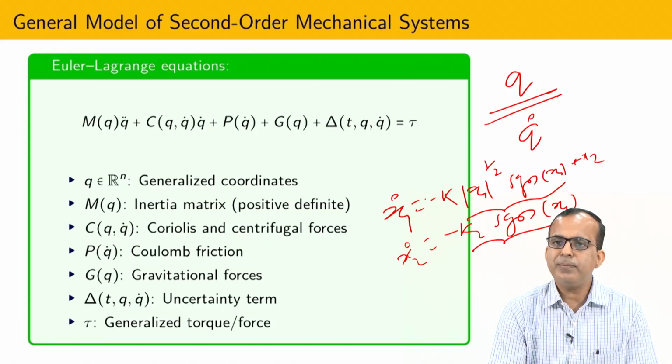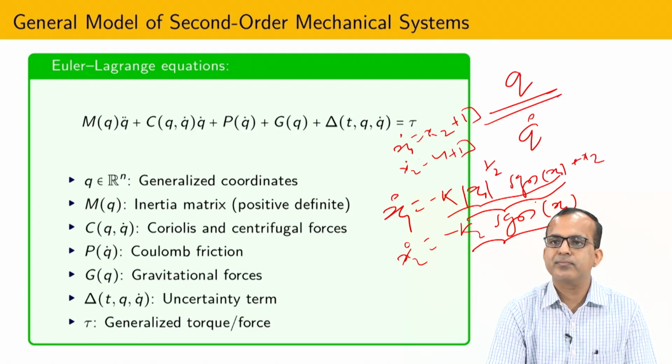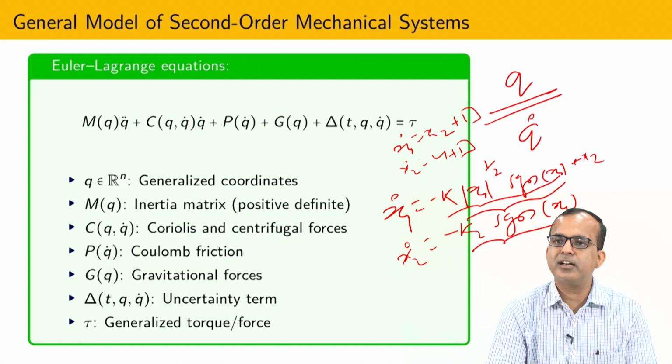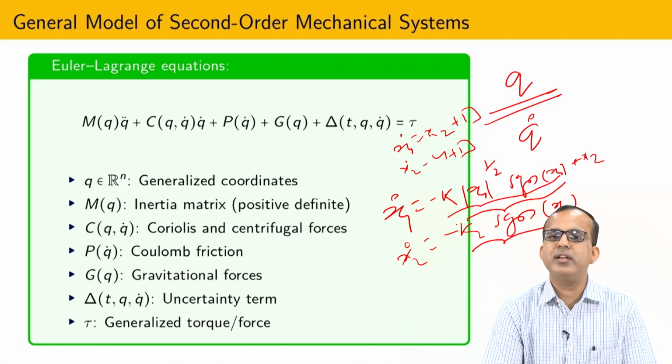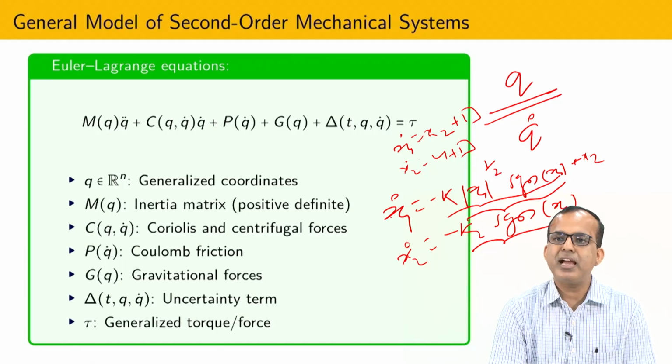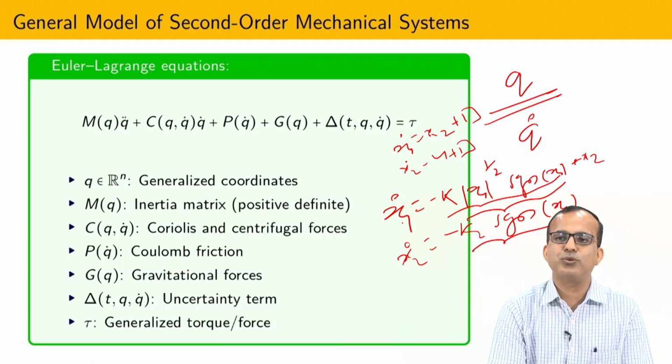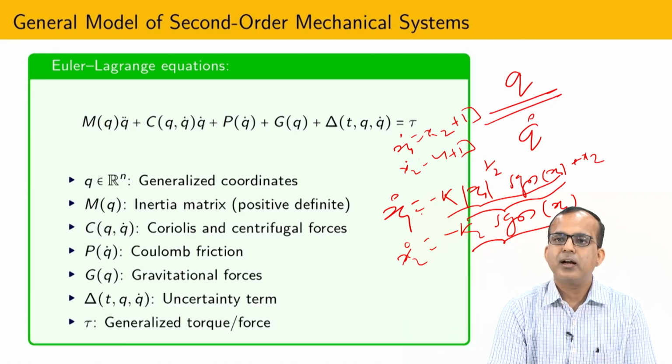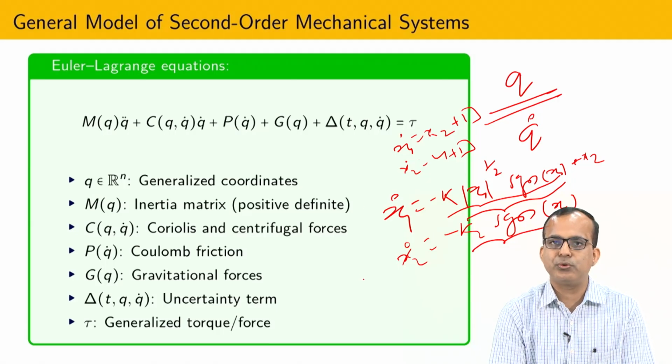So, if I have a system like x1 dot equal to x2 and x2 dot equal to u, I can add a correction term that looks like this, or a second correction term like this. In this way the whole structure is converted into the super twisting algorithm, and finally I will get x1 equal to 0 and x1 dot equal to 0, and in this way I can estimate the information of x1 from x2. So, that kind of thing we are going to look into.